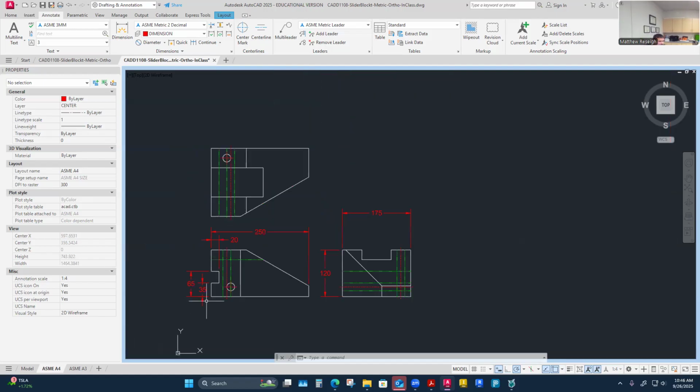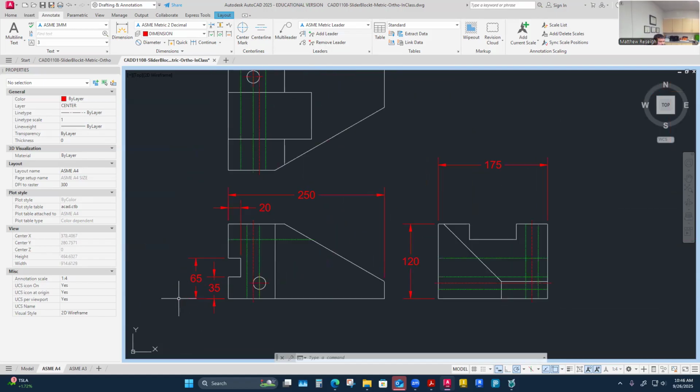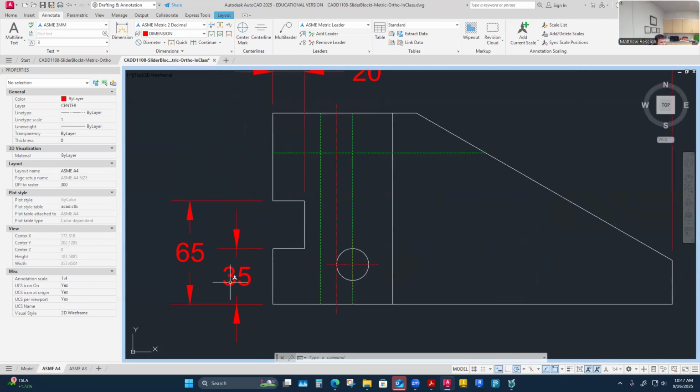There are going to be some more critical dimensions than others in how parts relate and fit together. Especially when you see a part in an assembly and how the other parts work with it, that is usually what drives where the accuracy has to be held. So I don't know here for sure, but the other way is maybe better because it's not chain dimensioning. And that's one thing that's pointed out on your rubrics: avoid chain dimensioning.